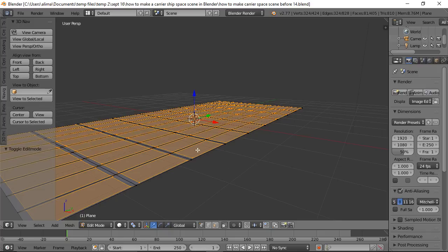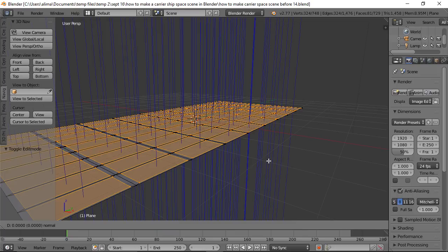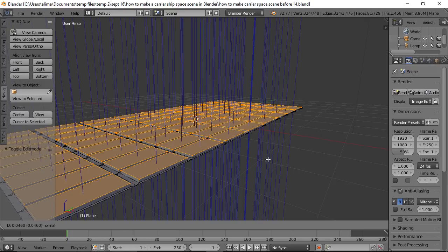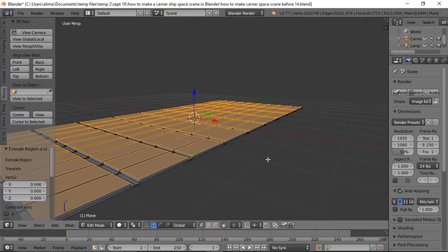Okay, with this view, that will allow us to see how much thickness we're adding a little bit easier. What we're going to do is press E to extrude. See those blue lines right there? Those are blue preview extrusion lines. They're showing us how our extrusion is going to go. So we're just going to push up slightly and then left click to lock that extrusion in.